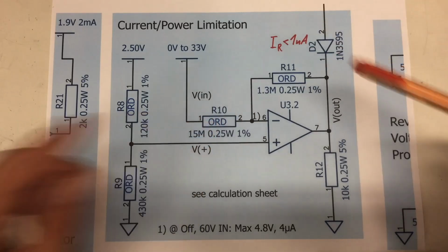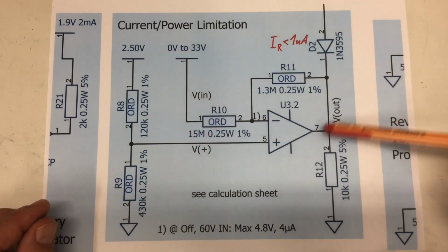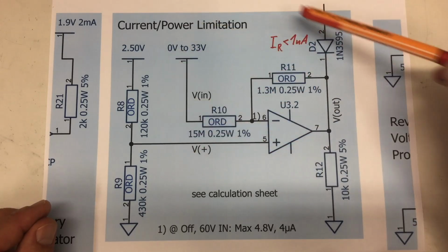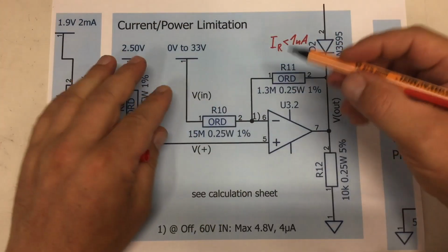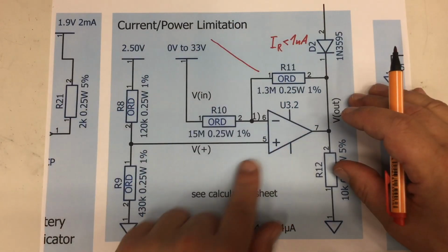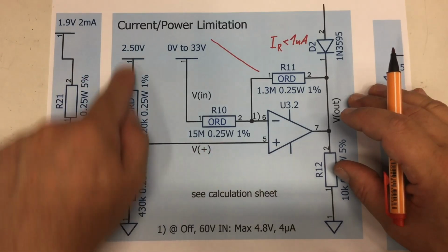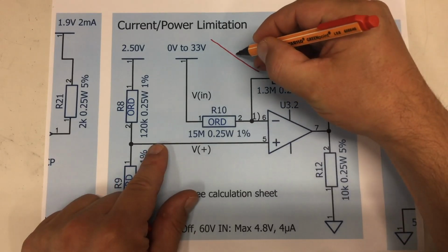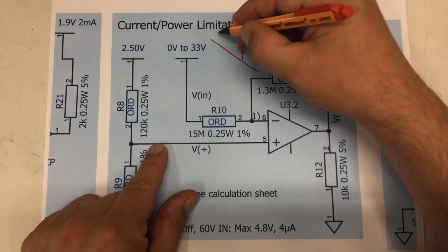And since my voltage dividers up there are quite high impedance, it's important for that diode to have a very low reverse current. The rest of the circuit consists of an op-amp in basically an inverting amplifier configuration. You remember our current limit curve goes downward, in combination with a single adder of a positive voltage. So we are actually shifting that curve, which would normally go through 0, a little bit.